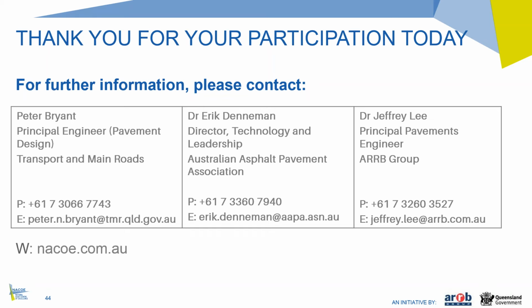Yeah, and I think that's actually a very good point. Historically, mixes in Australia simply have not been optimized for fatigue performance because there was no encouragement to do so in the specifications, and that's really one of the big changes here. It is very well possible to balance rutting and fatigue performance, as the ME2 mix designs show. So I think that's really what we're after here: come up with real performance-based design of asphalt mixes that will lead to superior products, and that encourages the use of those in our pavement design system. Steve, I hope you've got your clarification on those.